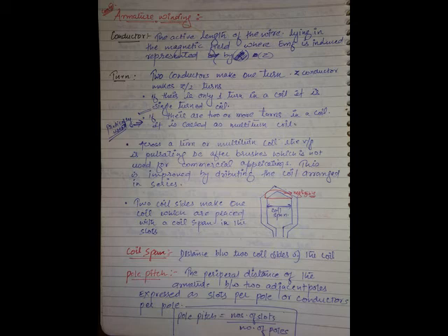Because here, what is the pole pitch? If you say 180 degrees mechanically, but what is the pole pitch here? It is varying, right? So always 180. If you say this point to this point, 180 electrical degrees. From this point to this point, how many electrical degrees? 180. From this point to this point, how many electrical degrees? 180. Let it be 1000 poles. Let it be 1 degree mechanical, but you will get 180 degrees electrical, always under a pole.